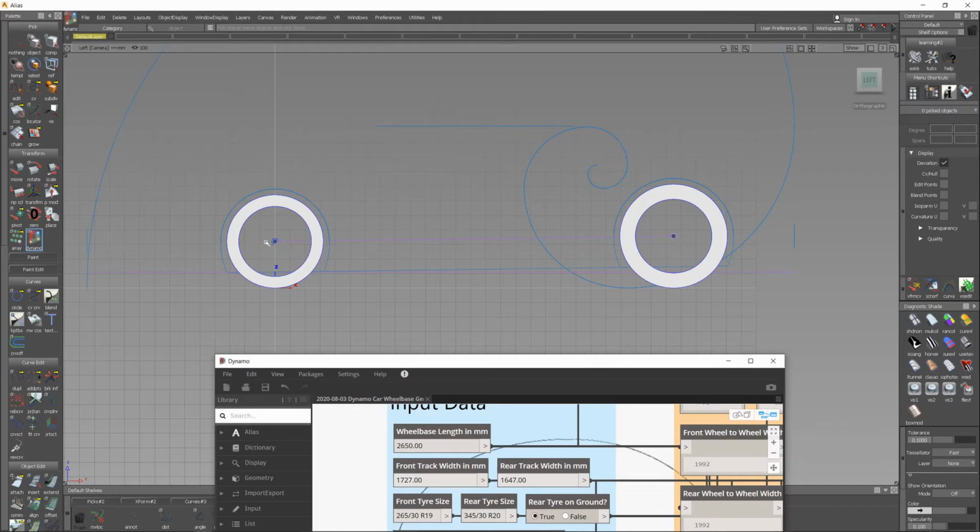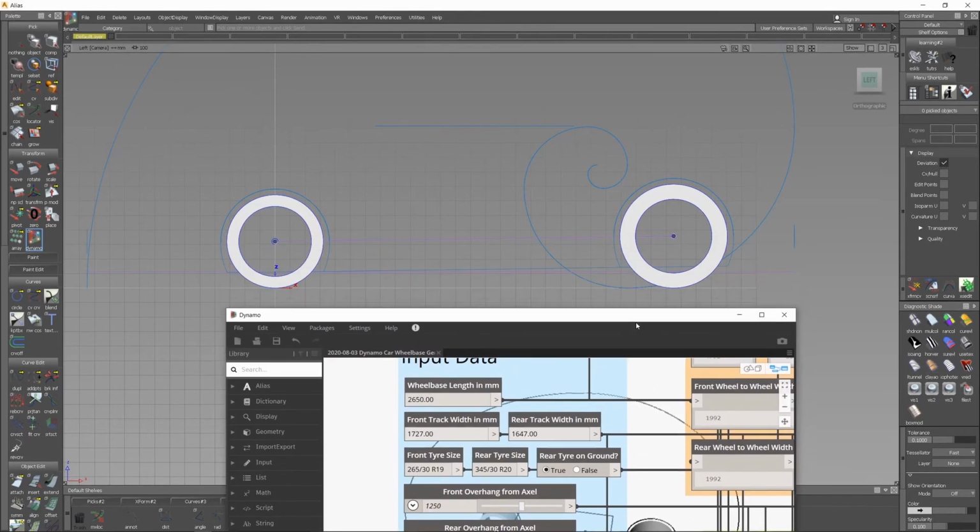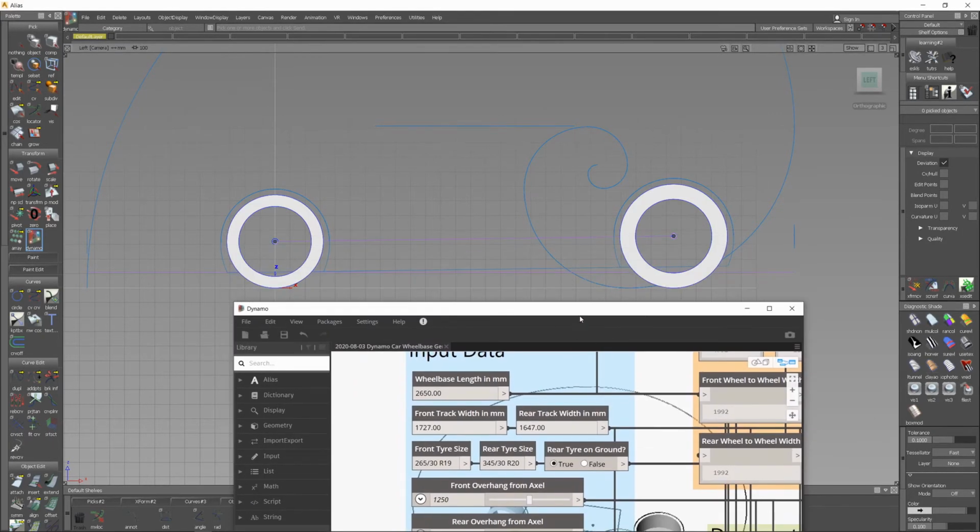Because if you think about it, the point from here straight across to here and then up, joining the center of the back wheel, actually forms a very thin right angle triangle. So you can use trigonometry to work out the amount that the rig should rotate for the rear tyre to touch the ground. So that's quite cool.